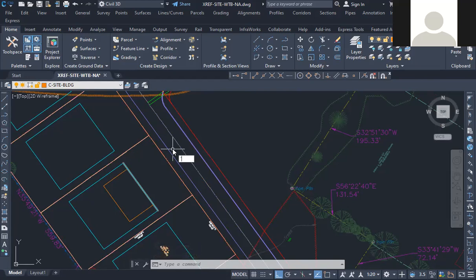Why? Why would I want to scoot the building back an additional foot from the VRO? Construction tolerance, right? Let's say that there's a brick ledge on the front of the house or a stone ledge, that they want stone instead of siding. Now the stone is out into the front building restriction. Would the zoning officer come out and say something? Well, let's not take the chance. Let's scoot the building back half a foot or a foot and be done with it. Okay. The driveway.